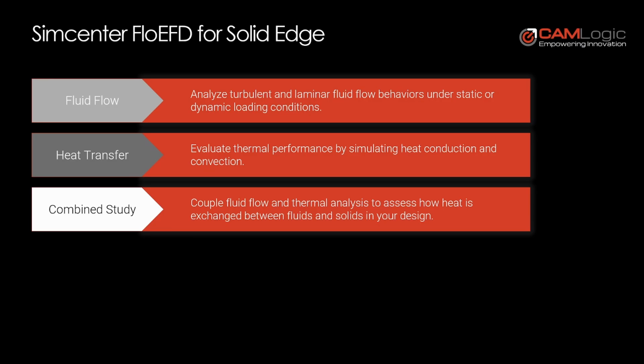You can also do a heat transfer study, similar to what we had just shown, by simulating heat conduction and convection, which would give you similar results to the study I had just shown. But you can also do a combined study, which is probably the most common use case, which couples fluid flow and thermal analysis at the same time into a single study, which shows how the fluid flows and how heat is exchanged and transferred between the fluids and solids.